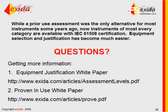Another question came in. If proven in use is done by the end user, how do you handle items being used for the first time? The answer is you can't. Don't use brand new equipment, equipment you've had no experience with in safety critical applications.